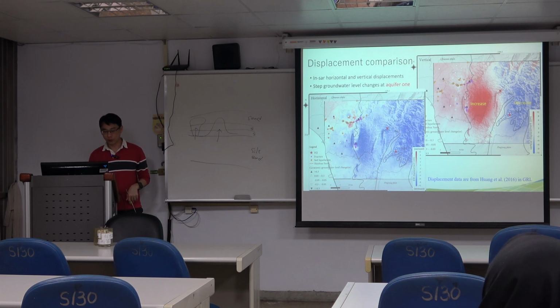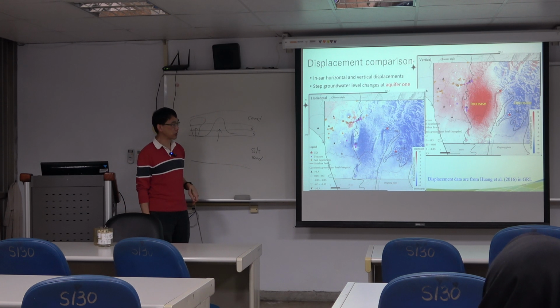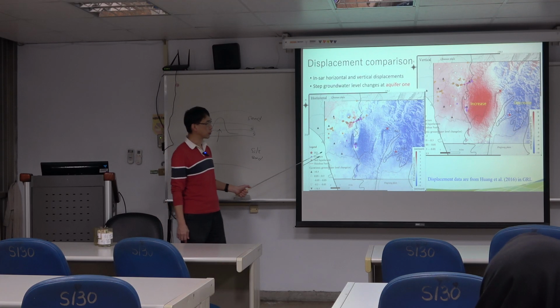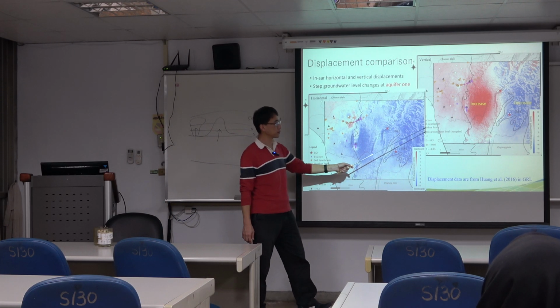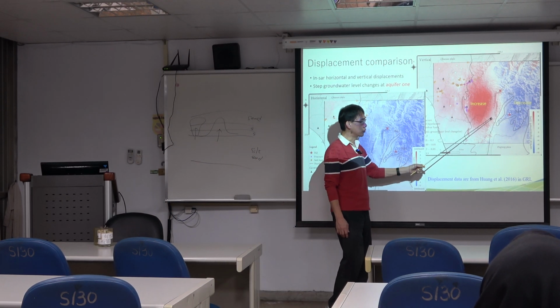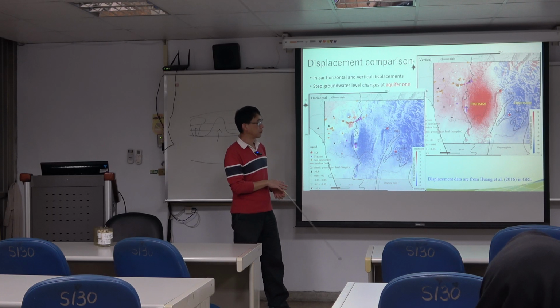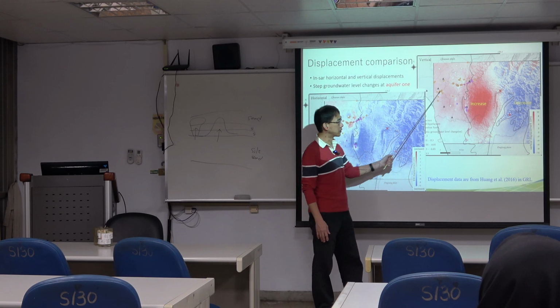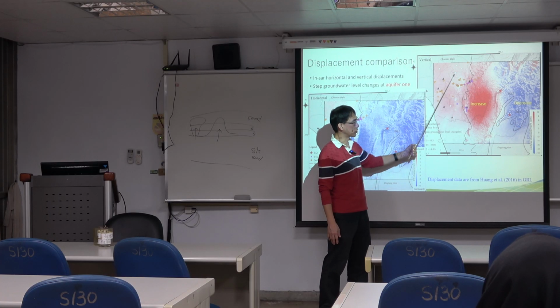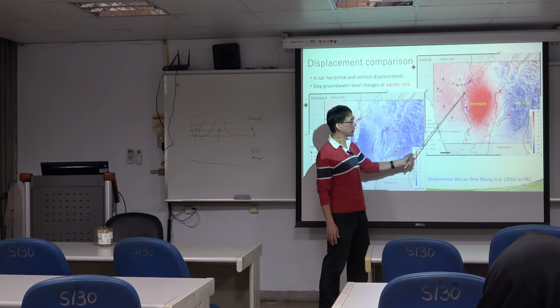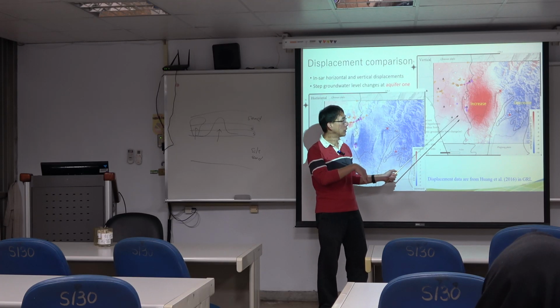And another, we try to take a look at the displacement field. That could be the horizontal displacement and vertical displacement, because they can be used in the InSAR system to detect the deformations. We can see there's an increase of the surface in some places, as I mentioned, with increased water pressure, but some places have decreased.